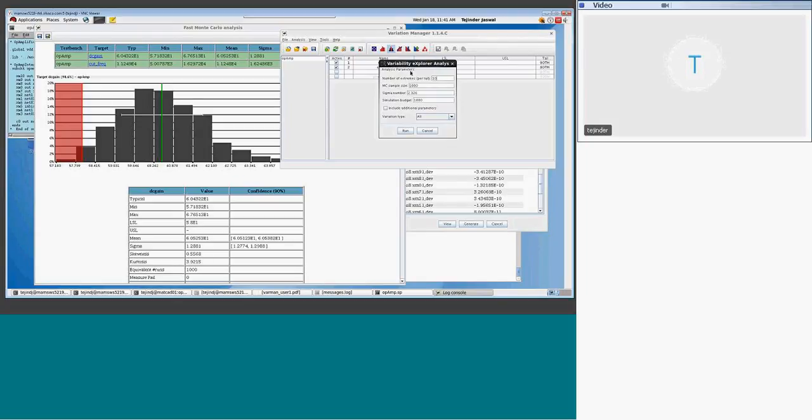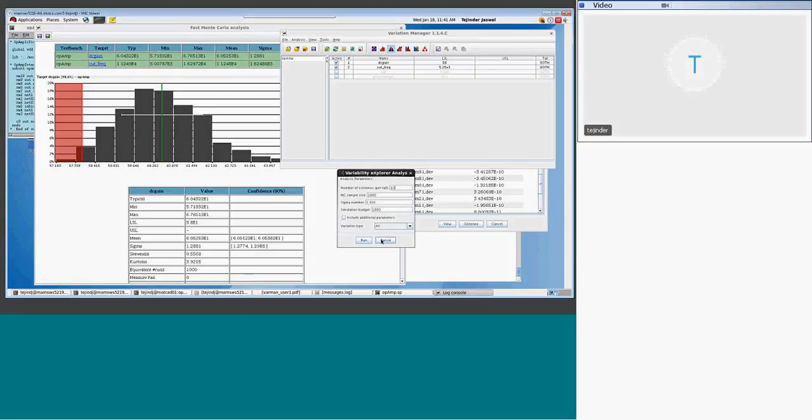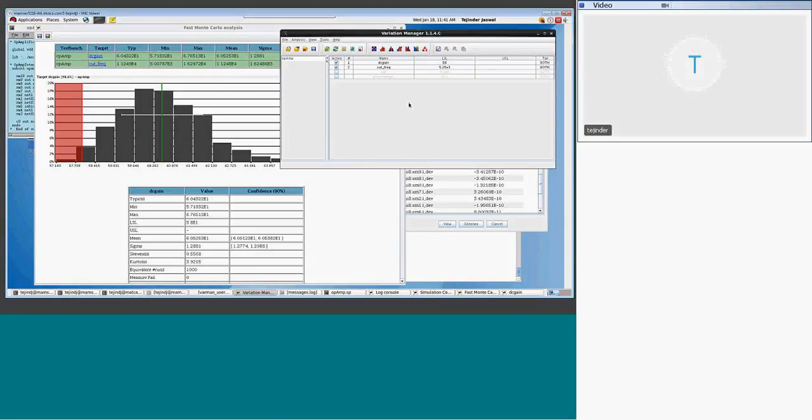Okay. So local variability, is that basically studying the matching characteristics? Local variability, you need to see it as an advanced sensitivity analysis. It's really very useful when you have big designs with many devices. If you want to do that with classical tools, you need a huge number of simulations. Local variability is based on a really innovative technique, so you can use it for big designs, but with a very limited budget.